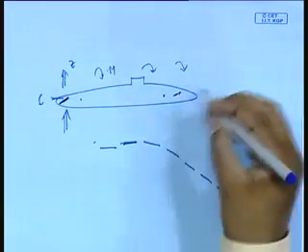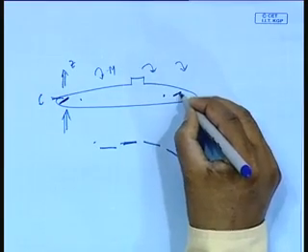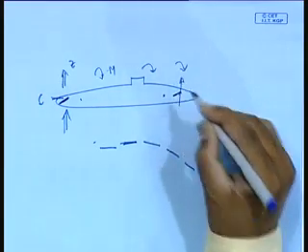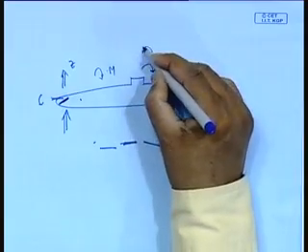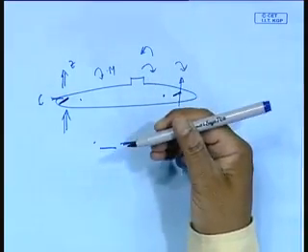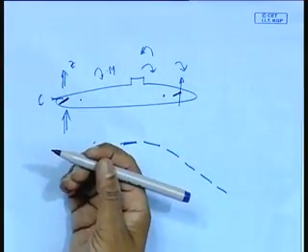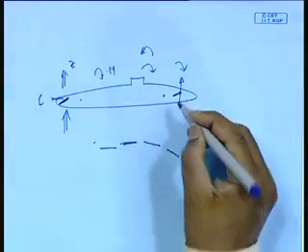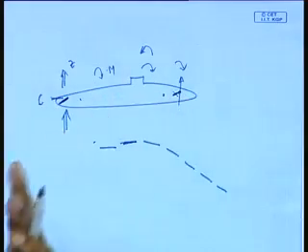what do I do? Remember that if I do it this way, then I am getting a force here and a moment there. What is it trying to do? They are in the same direction, both are in the same direction, up and nose up, for down opposite. So, for the bow plane, the heave force and pitch moment are in the same direction. So, there is no control problem as such, but in the stern plane you want to go down, but essentially you are giving an aft force, an upward force.